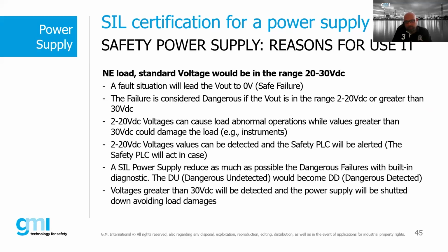A standard power supply is usually cheaper than a safety one, but this is because the standard one has components with limited operating range, so the final cost can be kept low. The quality of the internal components affects the lifetime of the device, and the safety power supply uses components with better operating range. Considering that often these devices work in harsh environments, this aspect shouldn't be overlooked. So a better design, besides overall better performance, also means that the device can work at a lower stress level, with less failure and considerably longer lifetime.